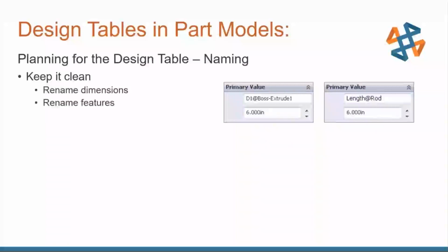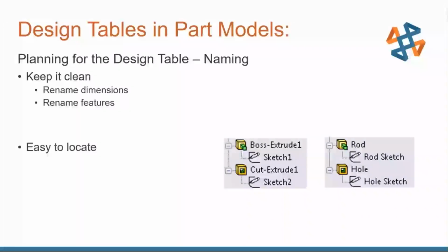I know I've done it, deleted a feature that I thought was insignificant, but it was very, very important. Got the tree blown up. Thankfully, I could undo back to safety. But if you just rename a couple of features, they're easy to locate in the tree. You can use the tree filters to find things effortlessly, but also make sure that you don't accidentally remove one of those features. That's extremely critical. Now for renaming, it's that left click, pause, left click, or you can select and use the F2 key on your keyboard, kind of the universal Windows hotkey to rename, works just as well.